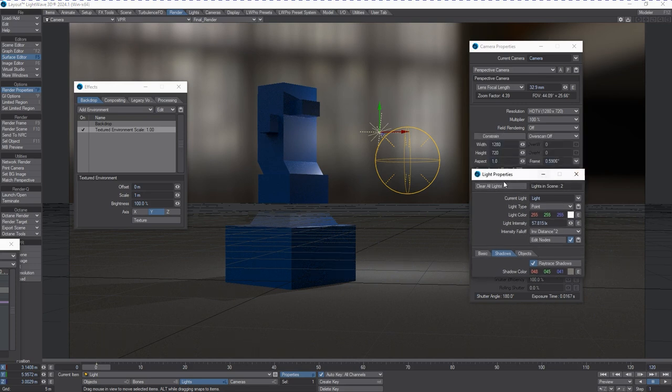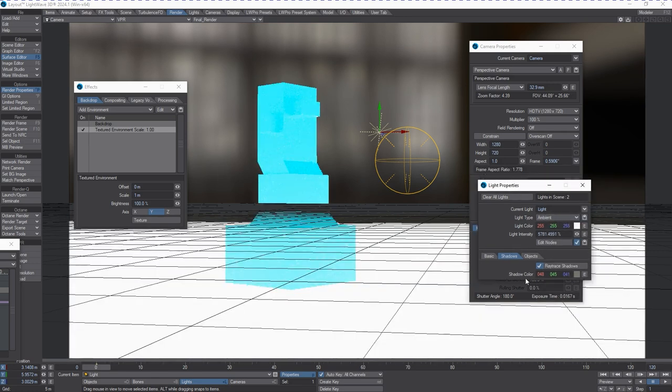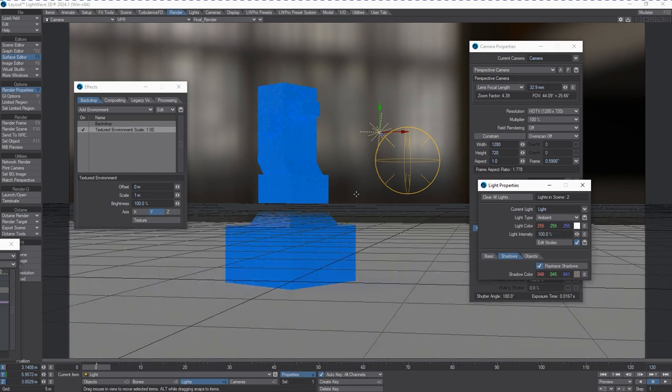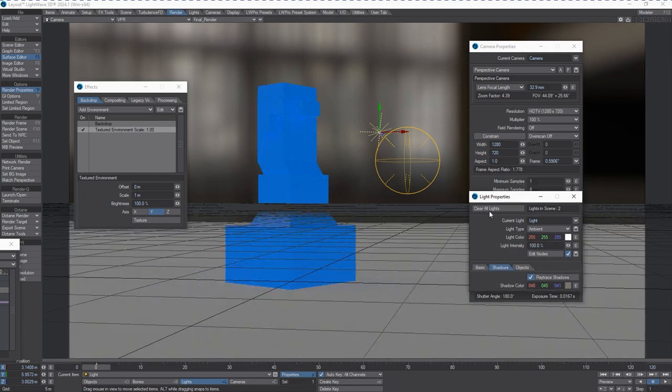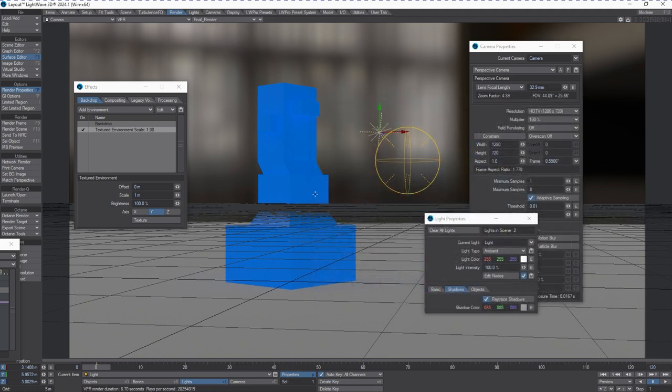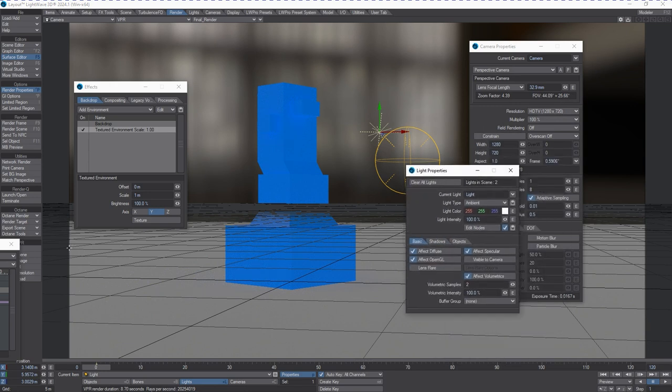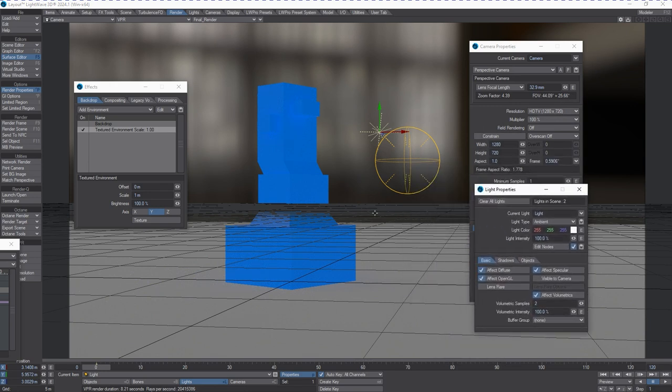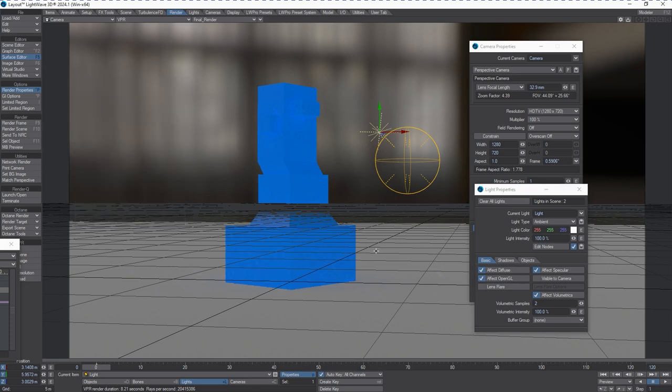Another light property that does a better job of doing this because it's specific to this type of thing is the ambient light. Now, for a while, the ambient light function was removed out of Lightwave, and we were expected to just get along with it, but due to request, developers put it back in because we absolutely needed it. And ambient lighting can be very handy for filling in gaps without having the render engine do the work of bouncing light using global illumination or throwing additional lights in to fill dark spots in, that sort of thing.